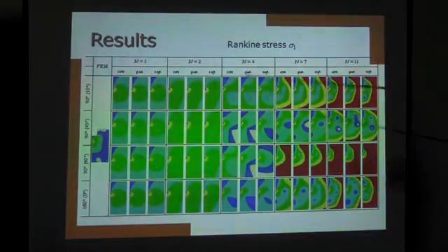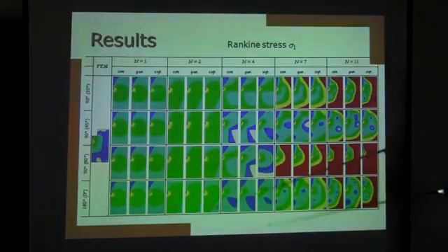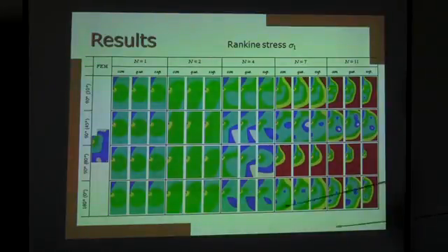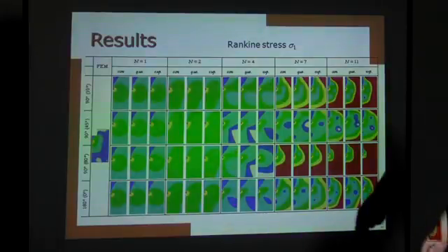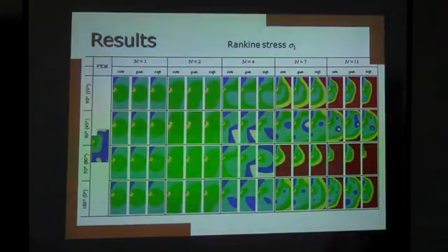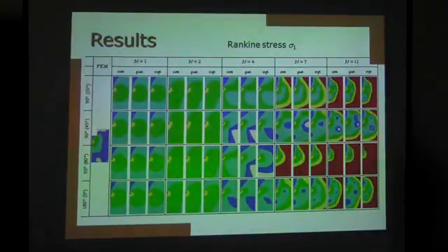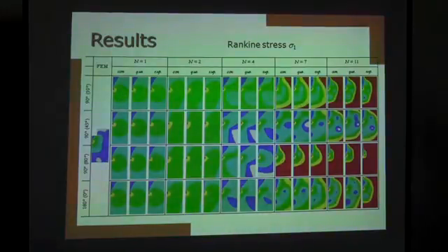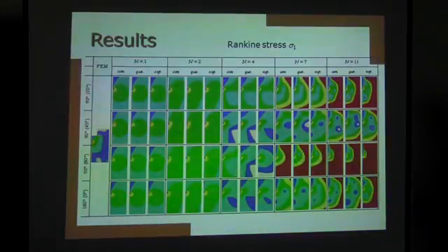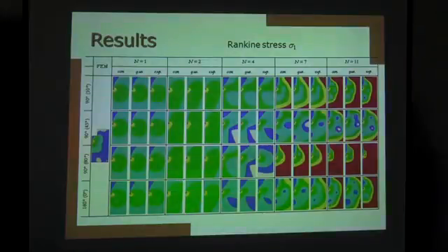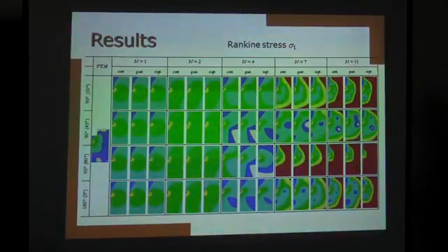As you can see, for the first two terms there are almost no differences, of course, because the description is just in a very small region near the crack tip. But when we use a higher number of terms, we can see that the stress field depends quite strongly on the selection of the nodes.